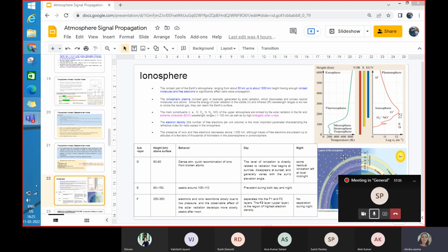Wet and dry portions are a different picture. They are the picture of the components of the troposphere. When the wet portion, that is water vapor, is influencing the signal, we call it the wet delay. And when the dry gases like oxygen, nitrogen, and so many other things affect the signal, that is known as the hydrostatic or dry delay.